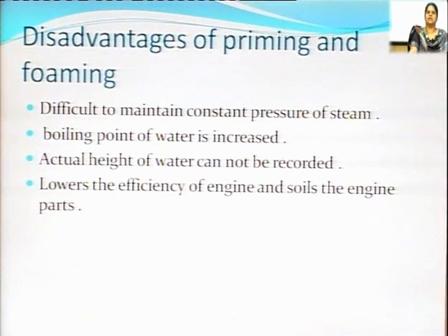Now, what are the disadvantages of priming and foaming? The main disadvantage is that we cannot maintain constant pressure of steam, and due to the presence of soluble impurities in water, the boiling point of water is also increased. Another disadvantage is that due to the presence of a large amount of bubbles, the exact height of water cannot be recorded.